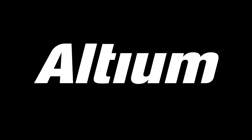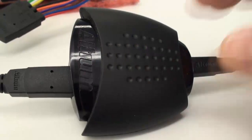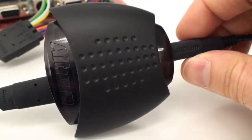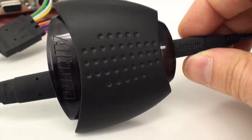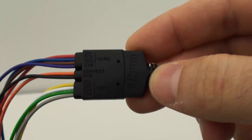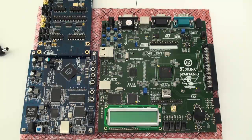You may already be aware of Altium Designer's phenomenal FPGA and embedded systems design capability. You might even use a NanoBoard. But did you know you could use almost any FPGA development board or production board with Altium Designer? Altium's FPGA Developer Tool, also called the DTO2, provides both hard and soft JTAG chain access to any board as long as you have the JTAG connection available. It can even work with some generic JTAG devices too.